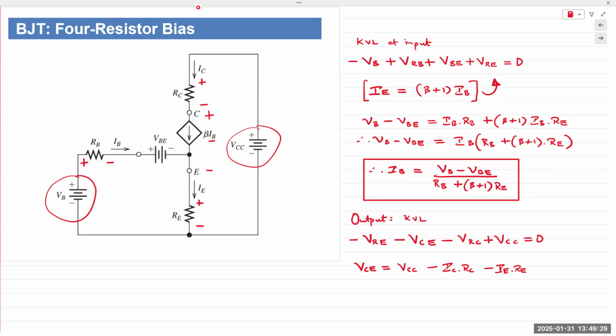In the load line analysis, we found the values for IB by plotting the load lines. If you perform a mathematical analysis, we need to find an equation that describes IB. So, apply KVL, rearrange the terms, and we obtain an expression for IB. And you can notice beta is there as part of that equation. On the output side, it's the same expression.